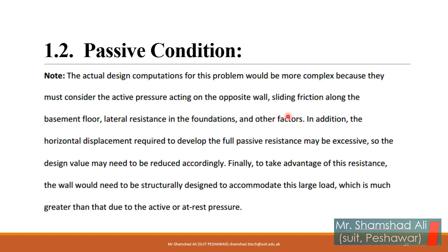The actual design computation for this problem will be more complex because you must consider the active pressure acting on the opposite wall, sliding friction along the basement floor, and many other factors. So this is basically a theoretical calculation; in a realistic calculation you have to consider the active pressure and the friction on the wall side, but we are just going to conduct a theoretical calculation.